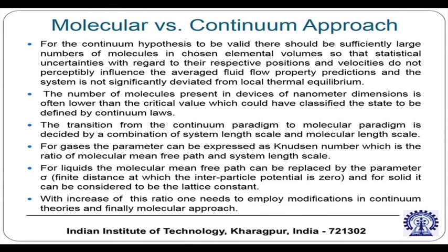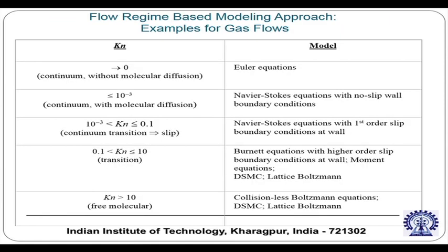With increase of this ratio one needs to employ modifications in continuum theories, and finally one has to go for the molecular approach. For gas flows we have already discussed various Knudsen number based regimes, and this is just a demonstration of what your simulation strategy should be based on the Knudsen number regime. Let us say you are asked to solve a problem of gas flow. What kind of simulation will you use? Based on the Knudsen number there is some guideline.